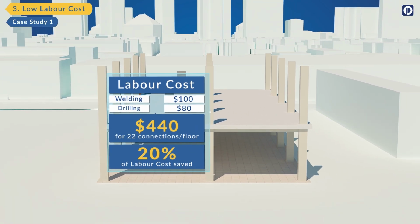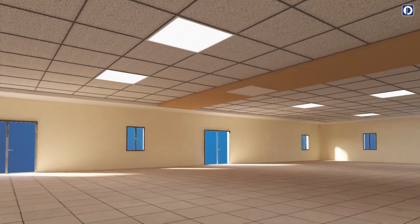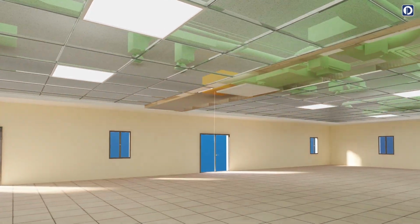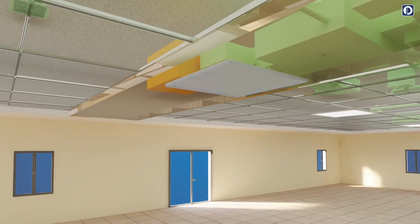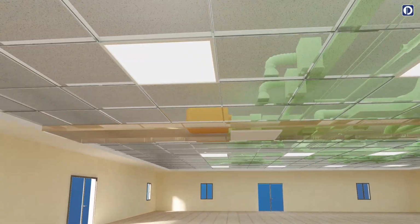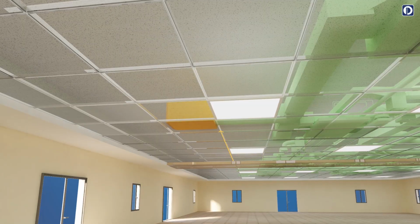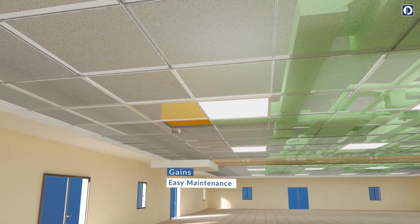Easy maintenance. Inline equipment, FPB, was placed above the hard ceiling as per design documents, where we would have to add an access panel for maintenance. After value engineering, we were able to move the FPB above the acoustical ceiling for easier access during maintenance.